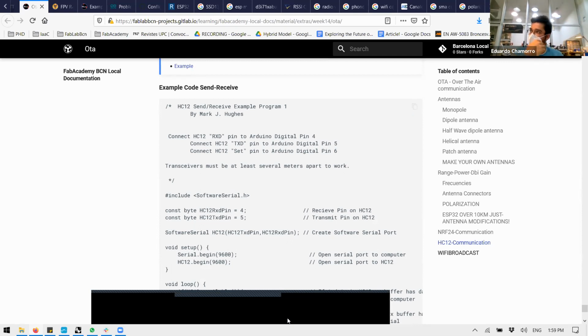If you're using specific protocols over the air, such as Wi-Fi, could you maybe not do jamming, but pollute the whole spectrum? Yeah, there are projects to use the ESP32 as a jamming device. You pollute with something specific and you send something specific to the device. That depends a lot on the protocol. In the case of jamming, in general, you emit in a specific band or all the bands, and you just send a lot of data at maximum power. I never went really deep into that, but in general, the generalistic approach is that one.